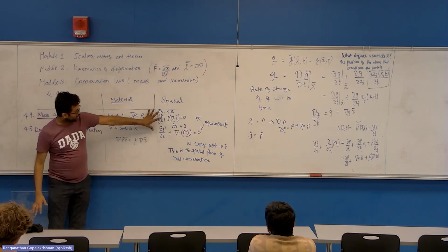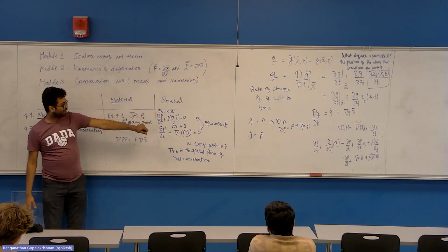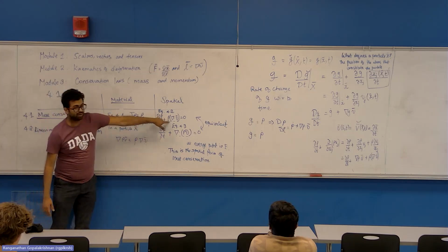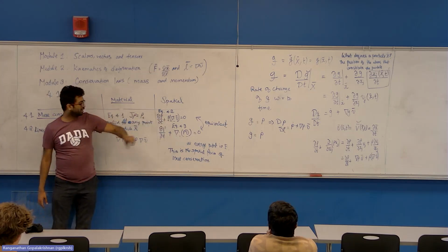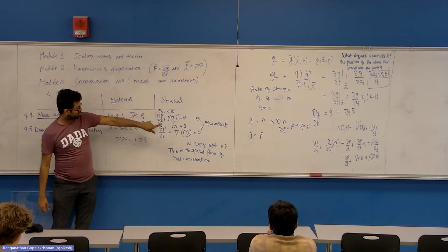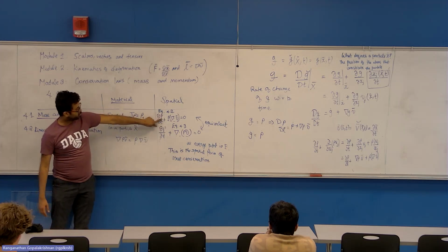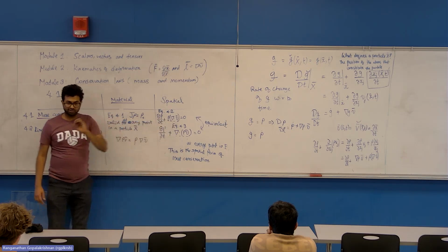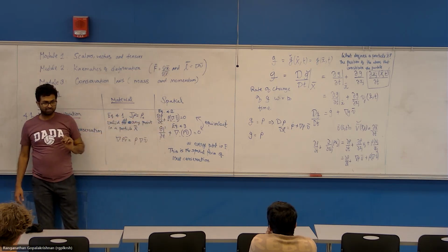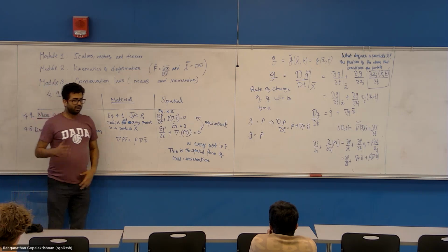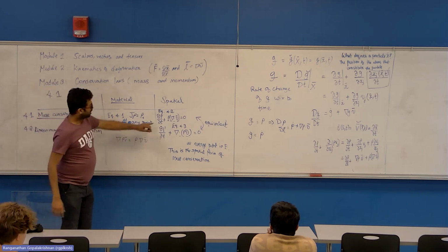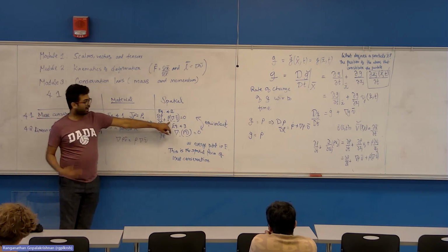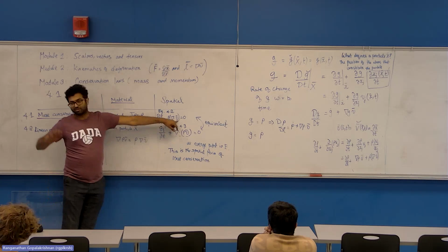So you have to solve this equation, and to solve it, you need to know initial condition, boundary condition. And not only that, this is just one equation, but involves three variables: density and three components of velocity. Okay. You should first recognize that you can't solve this equation by itself unless you know velocity from somewhere.